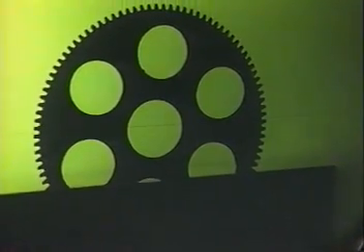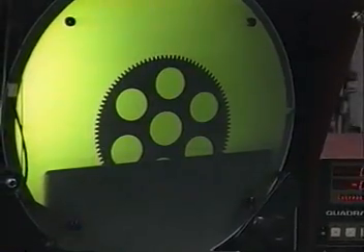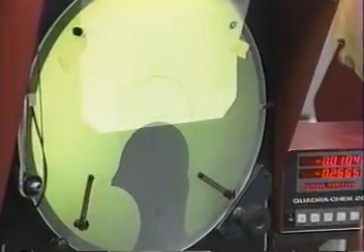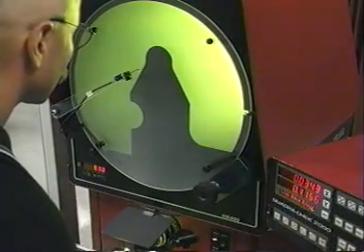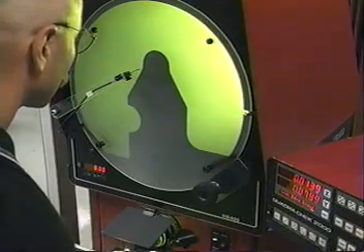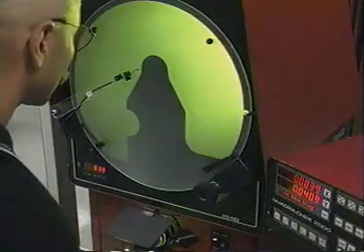Once a part is mounted and viewed, it can be measured by using either fine crosshairs etched onto the viewing screen to enter in coordinates, or by using overlay charts, which are drawn to the correct magnification and placed over the screen to quickly judge the conformance of the part to the specified tolerances. Additionally, many projectors incorporate auto edge detection systems that trigger a coordinate reading when light or dark edges are crossed.